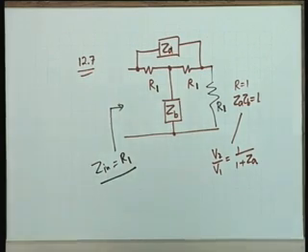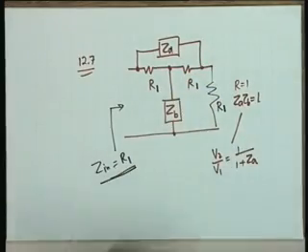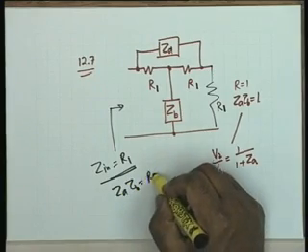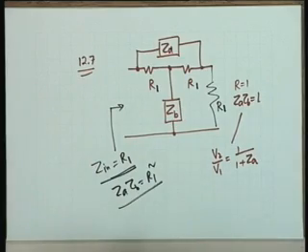Anything else? So when we assumed R equal to 1, we didn't assume, it's given. It's given Z is Z equal to 1; it's not given Z is Z equal to R square. That we have not proved yet. So it's not even stated that way. But this is a property of the network that if it is terminated in R1, then the input impedance is R1. And the condition for that is that ZA ZB equal to R1 squared, which fits in here, which only means that R is equal to 1. This can be shown. Okay, I will skip that part.